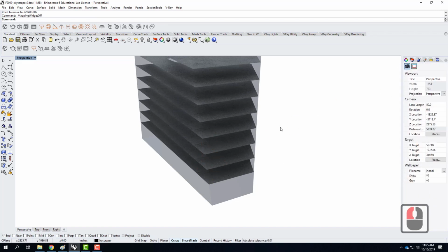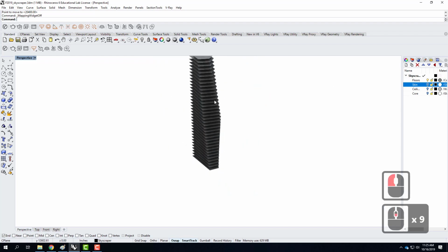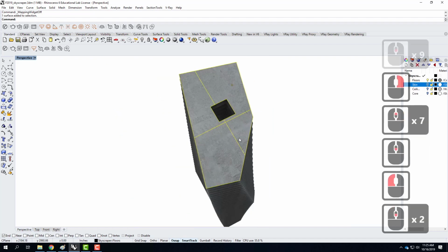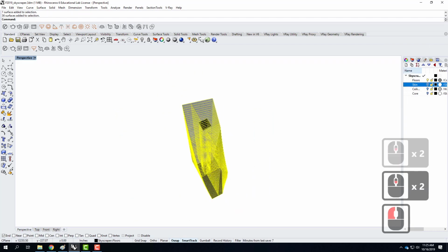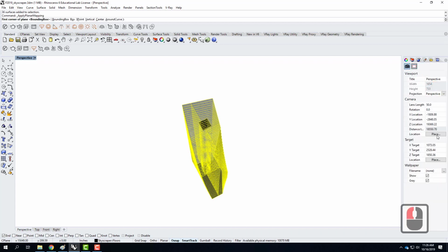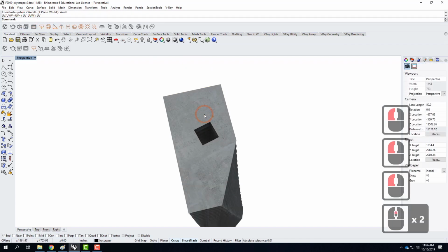And I want to look at the floors. They're on. Let me turn off the skin. There we go. I'm going to look up at the top here and see if the texture for the floor is right. Doesn't really look quite right yet. So I'll select all of the objects, and I'll go into my texture mapping again. I'm going to apply a planar mapping for all of these, coming down from the top. So we'll do bounding box, world, just a U and V, that's fine. If we look at it, it's a little bit better, but the scale is still off.